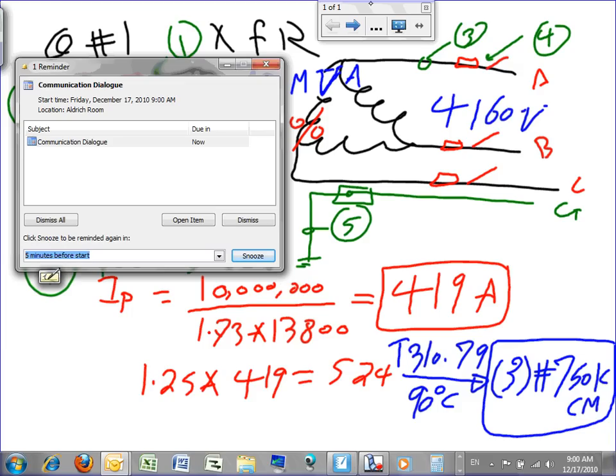77. Can you guys look at 77? 3 single insulated copper conductors in underground electrical ducts, 3 conductors per electrical duct. That's what you want. 3 conductors based on ambient. So if you look at this, it might be the best scenario for us. Detail number 1. Just because of the size, I'm going to change the table, because you might not be able to get that size.